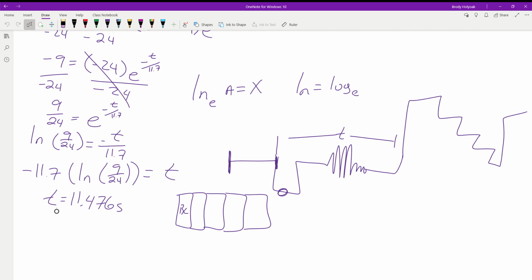Any questions about solving for these circuits? Okay. You should be able to take most of the quizzes. Let me look at them real quick. So you've got DC capacitors and charge: charge in coulombs is equal to capacitance times voltage. You've got capacitors in series, capacitors in parallel, capacitors in series-parallel, and now you've got capacitors and time constants, and the double points of capacitors and time constants. Double points. There is a triple points, but we haven't talked to there yet. Okay, that's all I've got.